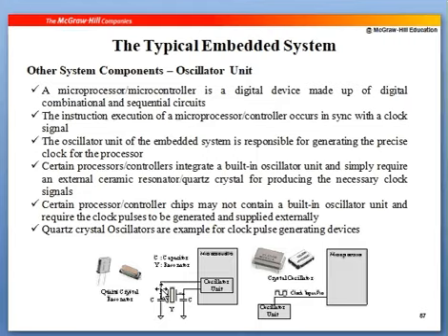These two are used to tune the frequency. If you want to vary the frequency of the circuit, you can use these capacitors, and this resonator circuit will create the frequency, which is connected to the oscillator. So the oscillator unit you have is just having two wires, and the frequency is generated using this resonator.